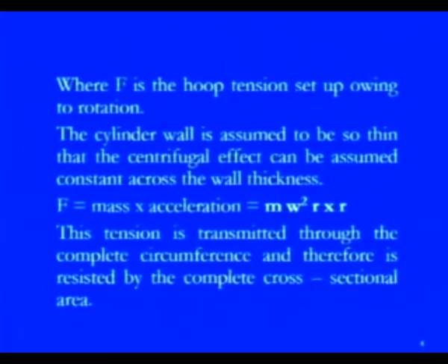That means whatever the centrifugal forces are, they are acting uniformly. So whatever the deformation is, it is also uniform. That means there are no stress concentrations, or distortions that differ at different regions. So as you see, we discussed that the hoop tensions are there at the diametrical portion.